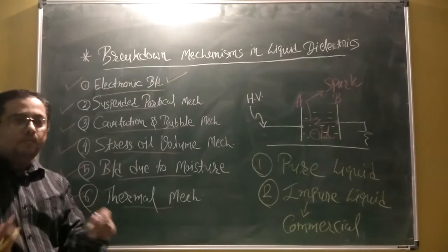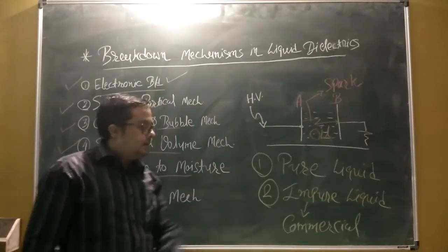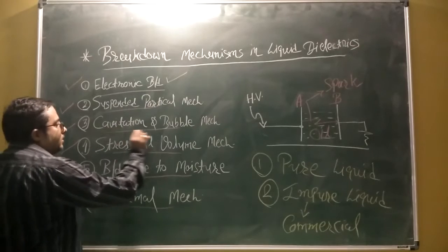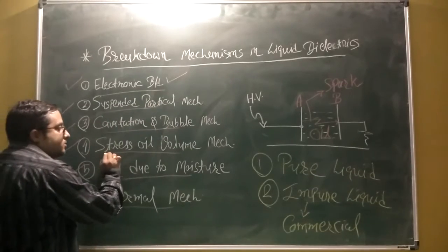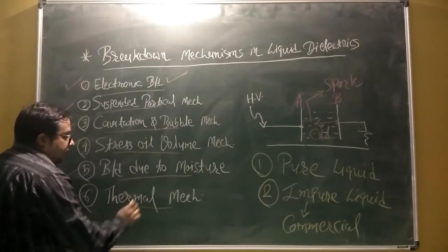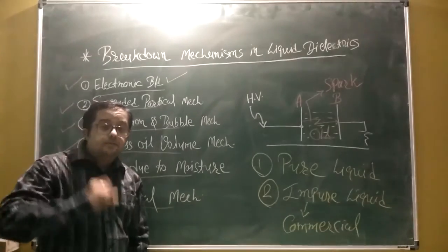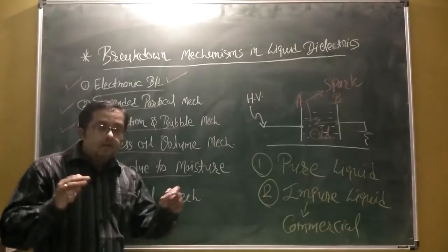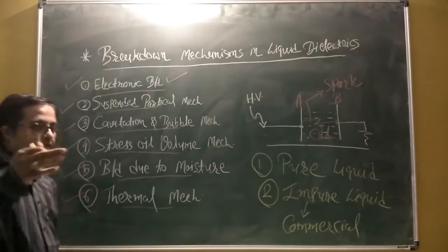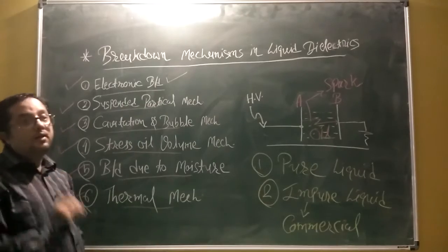As there is no impurity present in the liquid dielectric, the suspended particle mechanism is absent, the cavitation and bubble mechanism is absent, the stressed oil volume is absent, and breakdown due to moisture content is absent. But when this pure liquid ages successively, you can observe all these processes as well.